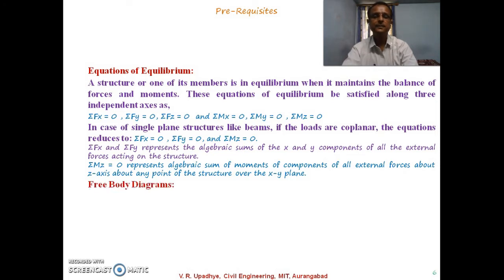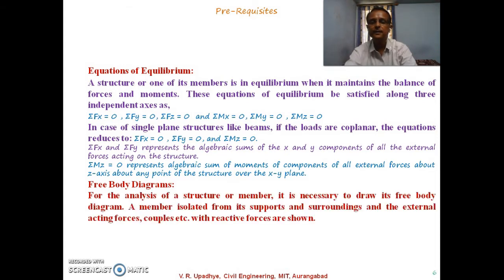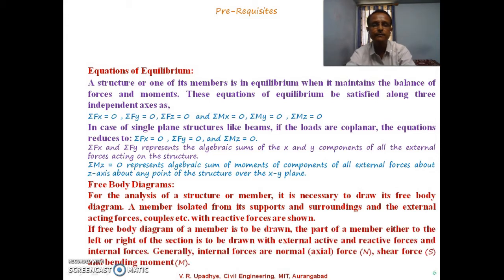Further, we will discuss exactly what we understand by free body diagram. For the analysis of a structure or member, it is necessary to draw its free body diagram. A member isolated from its supports and surroundings, and the external acting forces or couples, etc., with reactive forces are shown in those diagrams.